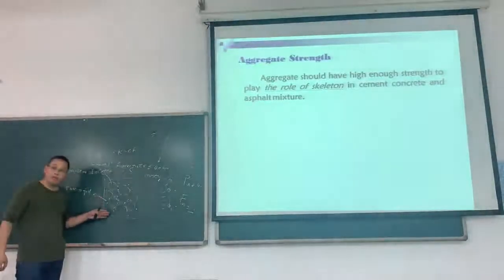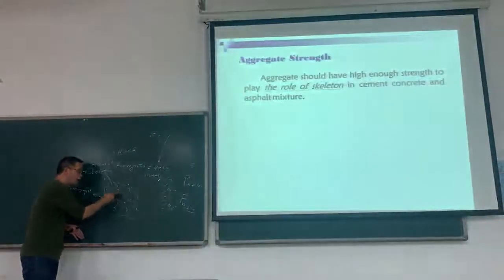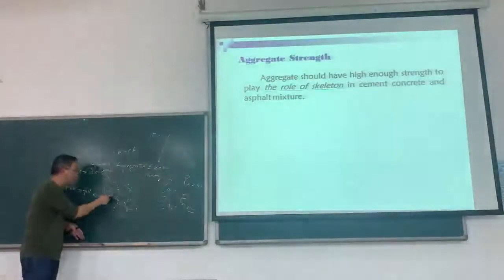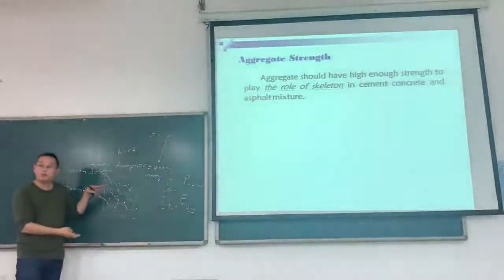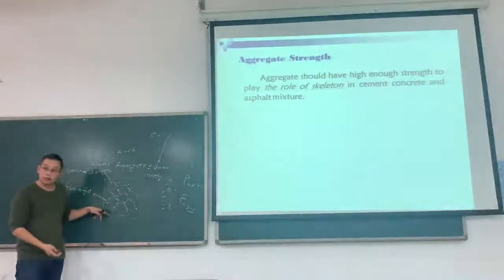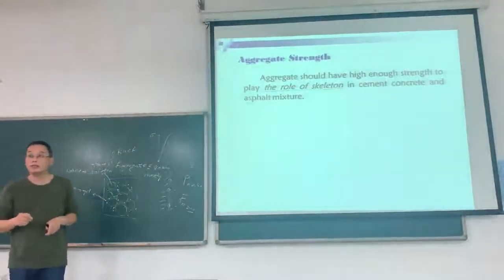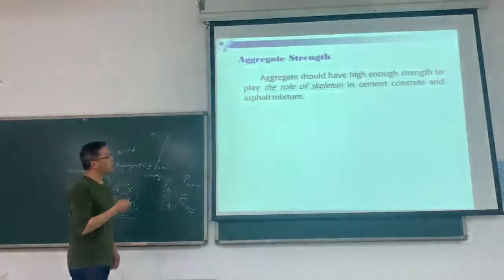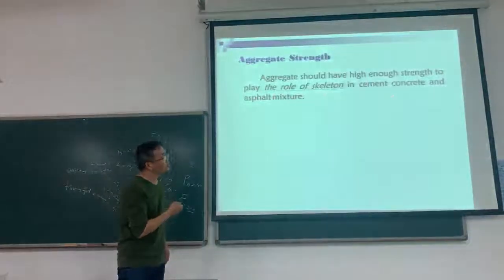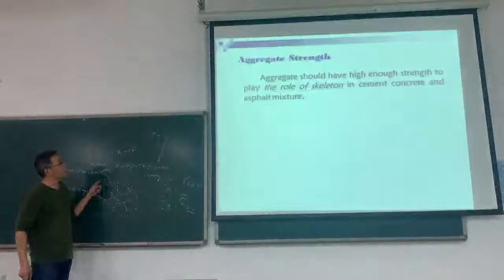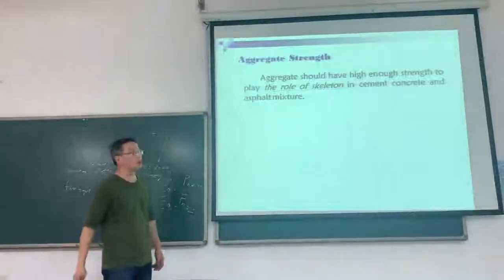So for the concrete, the function of the coarse aggregate is to be a skeleton of the structure. For the strength of the structure, the strength of the aggregate is also very important. So the aggregate should have high enough strength to play the role of skeleton in cement concrete.